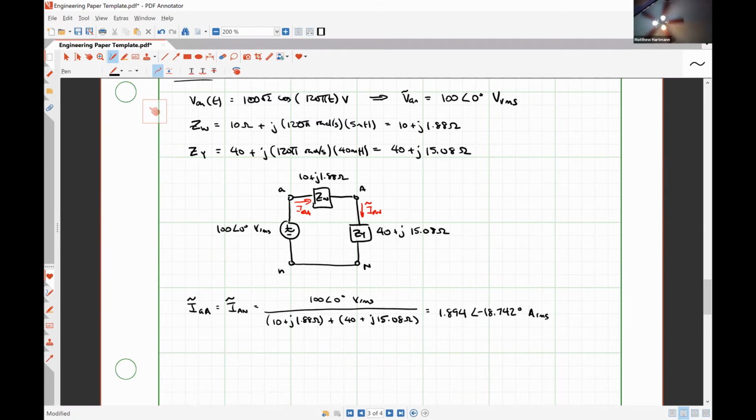So now that we know that current, that's practically the only thing we need to get at least A and B solved. Let me explain why I say that. Let's look at A, where we're trying to find the reactive power absorbed by the load. We're going to use the complex power absorbed by the load to find it, because my preferred methodology is to find the complex power for everything and then use that to get the other pieces of information.